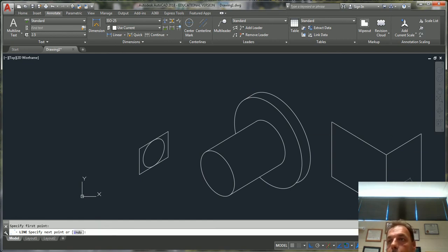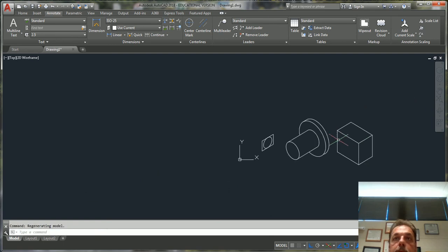So it's pretty simple. And don't use the offset command. Use your copy, okay, to copy the geometry. Pretty easy. Use F5 to get to the right plane. F5 to go that way. Trim, TR, enter, enter. So basically I've made a nice little box right there.